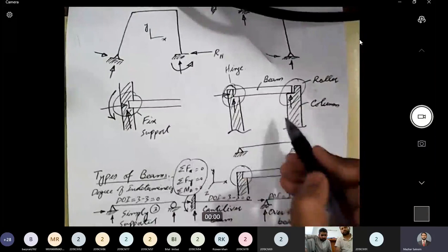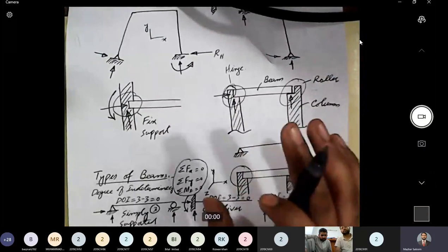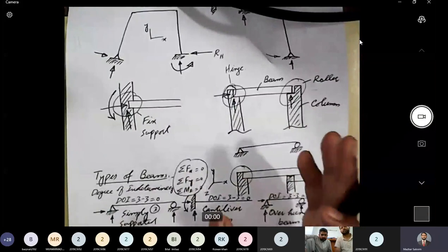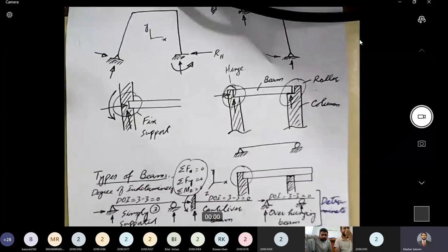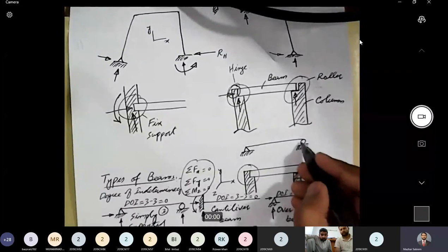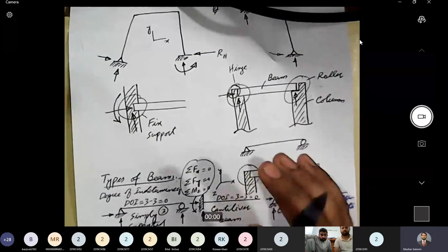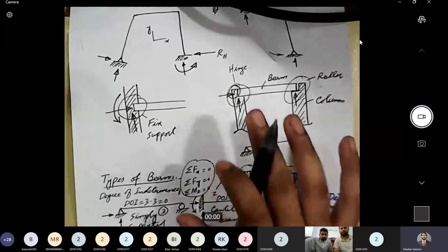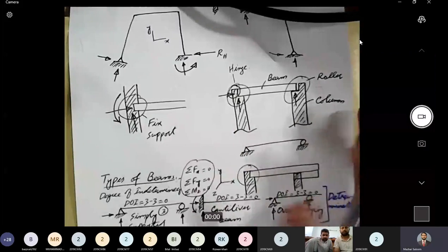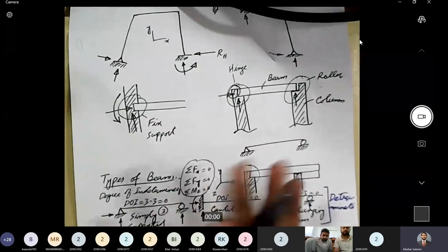That would be the case in some cases, for example, in case of bridges, where we actually place a roller under the bridge. This brings another important point: sometimes students think that if I'm saying the support is a roller support, there would be an actual roller placed under the beam. In buildings, in maybe 99% of cases, that's not the case.